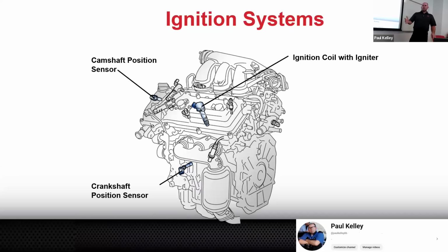Great. So if I tell the customer, as a matter of fact, it's the coil because the misfire followed, I would give them the option. I know it's the coil. I can guarantee it's the coil. However, if we replace your coil for cylinder number 3, I'm good with that. This is the price. But if you have another coil that fails, it's going to feel the same. It's going to run the same. You're going to get the same check engine light. So I want to let you know that you had one coil fail, and another coil may or may not fail soon. I don't know.